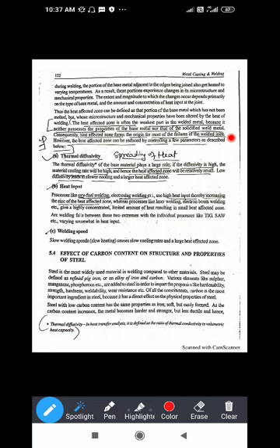Then next one, heat input. Heat input means what? Processes like oxygen fuel welding, electroslag welding, etc. use a high heat input, thereby increasing the size of the heat affected zone. Have you seen gas welding and electrical welding, where the rod is used? In gas welding there is a torch, and the flame comes out of that torch.